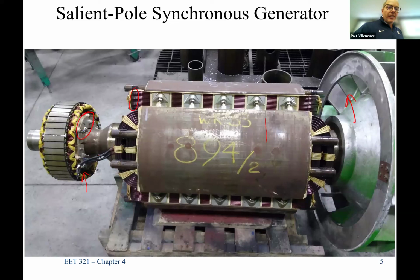And over here, if you look really closely, anybody want to guess what those are? I'll give you a hint. If you're an EET, John Allen will be very disappointed in you. If you're an ECE, Nuri Imantologu will be very disappointed in you. For semiconductors, they're diodes. Those are diodes. You need DC, right? So you only have two wires going there. So you get the rectifier bridge and you build it onto the end of that rotating part.